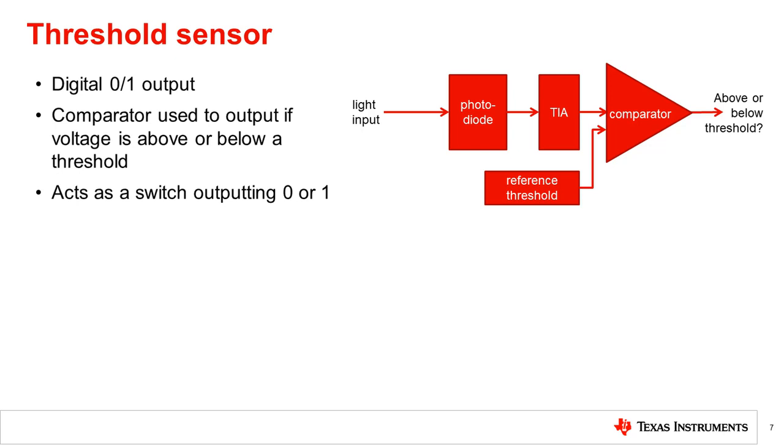With these sensors, the microprocessor can use a general-purpose I/O pin to read the sensor output, eliminating the need for an analog-to-digital converter. The 0 or 1 digital value is also less susceptible to noise, though multiple sensors still require multiple signals to be routed. These sensors may also include temperature compensation. For applications requiring an irradiance value rather than a threshold, there is another sensor type that solves a number of challenges with using an analog output sensor while still providing the irradiance value as output.